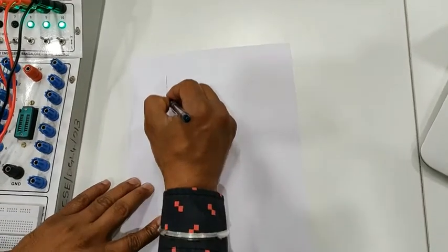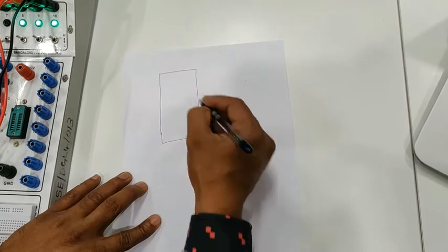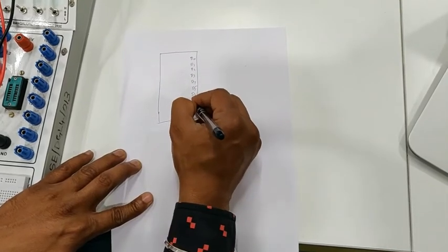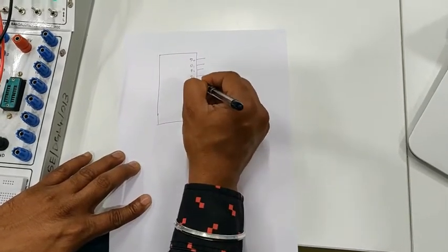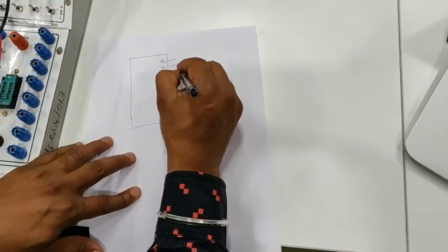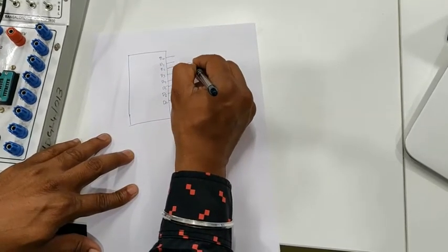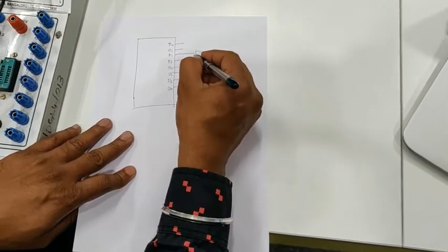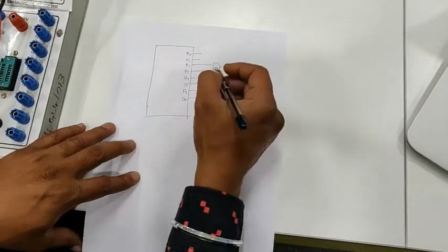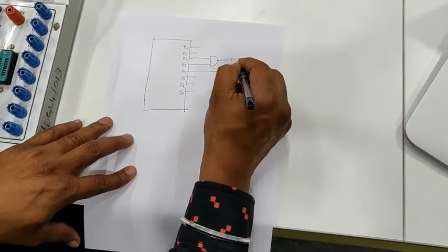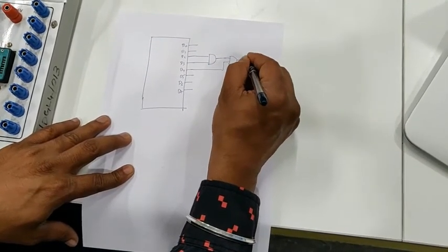So let us take 2, 3, 4. Let us take another one also. So this is your decoder, D0, D1, D2, D3, D4, D5, D6, D7. So 8 outputs. I'm writing only the output side. So this is for 2, 3, 4. For 2, 3, 4, you put one AND gate, because actually only one AND gate is enough, but we are using 2-input AND gates, so using 3. So 2, 3 and then 4. So this one, and then you have one more AND gate. So this is your F2, not F2, it is F2 dash.